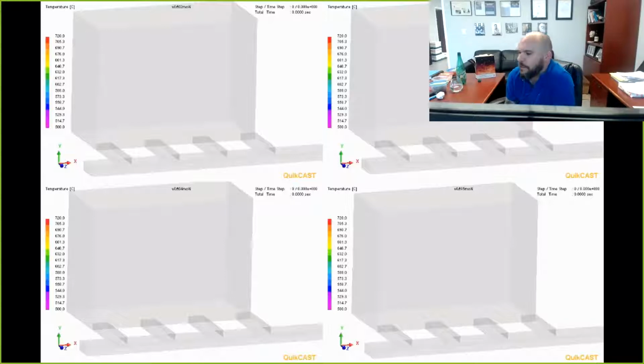We know that the conical pouring cup is a disaster. We're going to take care of that in a few minutes. We've still got the issue of velocity to deal with because we can't use a naturally pressurized fill system and reduce velocity by manipulating cross-sectional area, not in the way that it was done. And so now we have to realize that we've got a velocity problem to take care of.